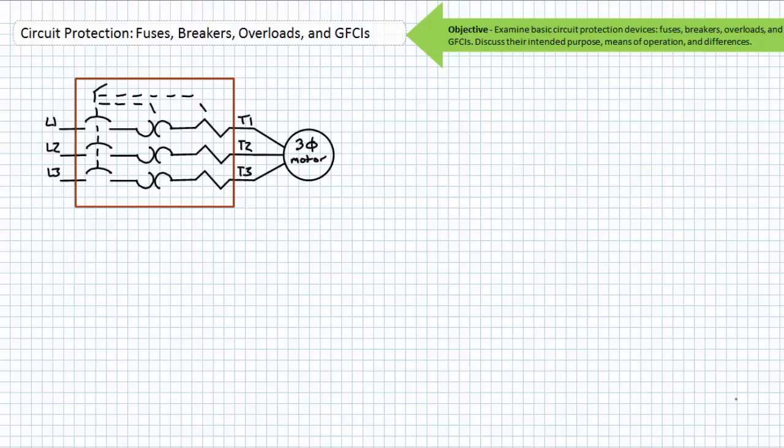An example of an overload condition might be an electric saw hitting a knot in a piece of wood or your electric car making a steep climb. If the circuit breaker was undersized, the system would experience what is called nuisance tripping, and every time you hit a knot or went up a hill, the whole system would stop and need to be reset. Not the most ideal of situations when saws are routinely asked to cut through imperfections and cars are routinely driven up hills. Overload conditions only become harmful if they're sustained, for example, the locked rotor on a motor.